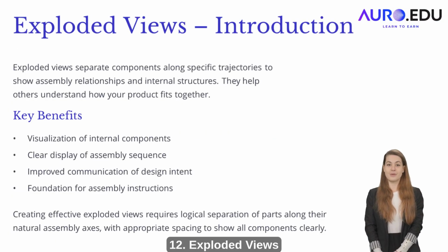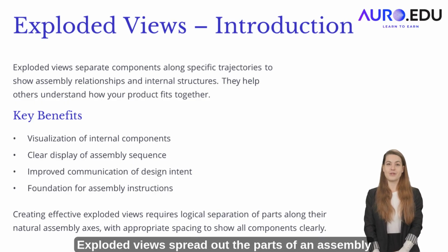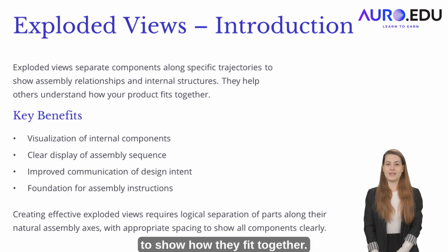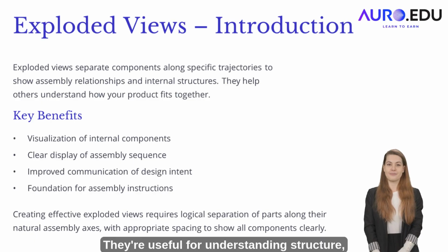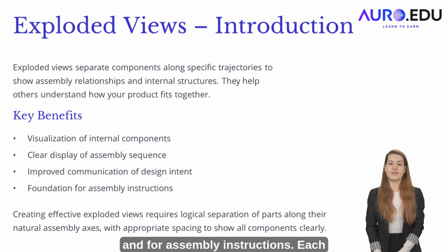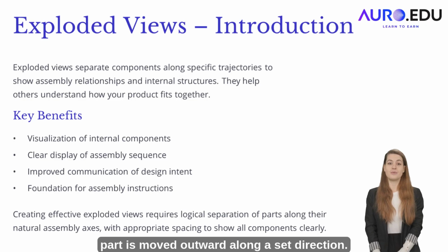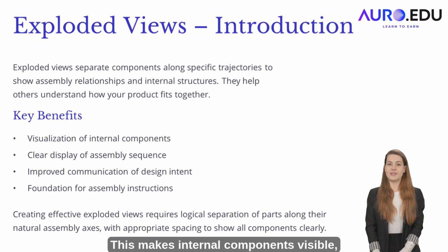12. Exploded views. Introduction. Exploded views spread out the parts of an assembly to show how they fit together. They're useful for understanding structure and for assembly instructions. Each part is moved outward along a set direction. This makes internal components visible and explains the product visually.